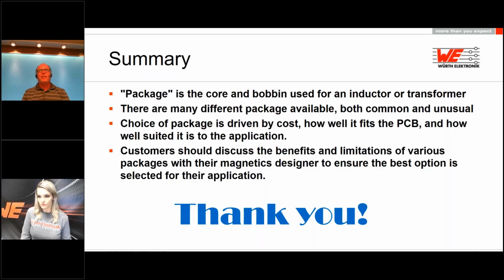The other consideration is margin tape only gives you creepage distance where the margin tape is put. Sometimes within a transformer where there are high safety distance requirements, there are almost, I don't really want to say hidden areas, but areas that are not intuitive, where you might have a creepage distance issue. In those cases, triple insulated wire will solve that issue, because you're guaranteed that wire is insulated for safety all the way through its entire winding. So the only place in those cases you need to worry about with triple insulated wire is right at the connection to the pin.